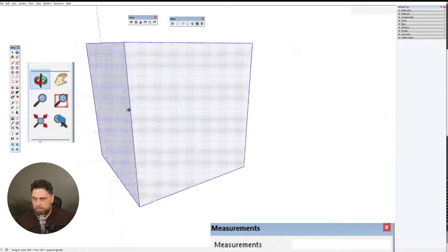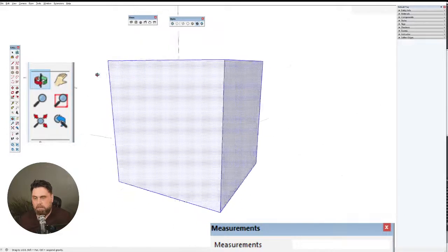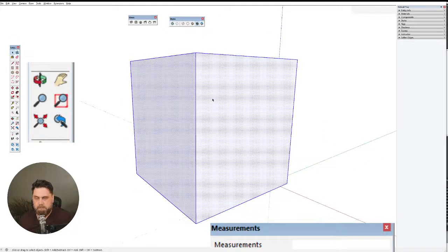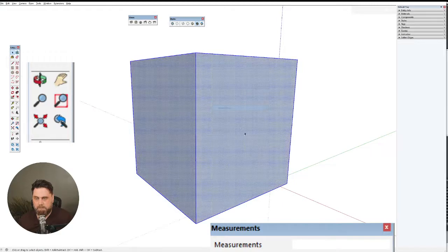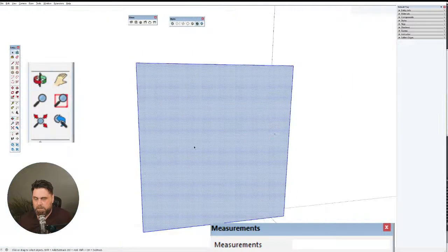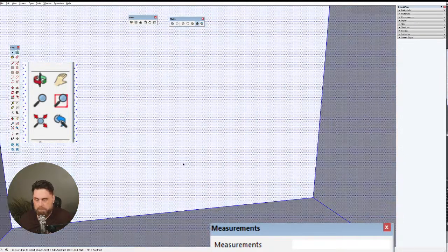All right. So we saw how the navigation works in the middle of an operation. So let's just practice here. And now we're going to do one other thing. I want you guys to triple click and then right click, go to reverse faces. And now I want you to come here and try to get inside the cube. Watch what happens. So zoom in and look. It seems like you're not going to get through because you're zooming forever, and then suddenly you break through.